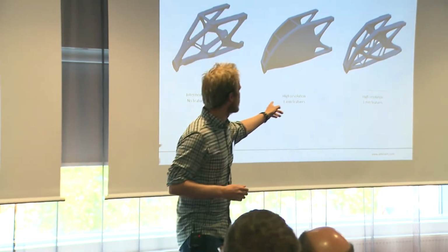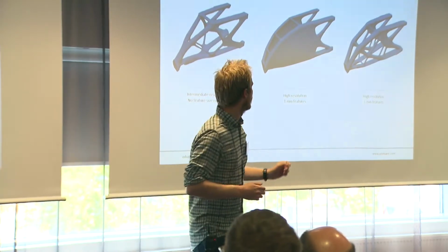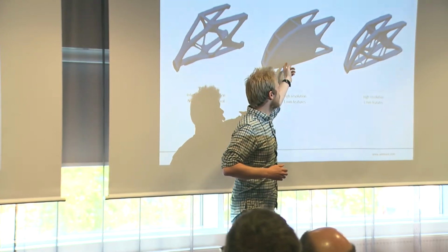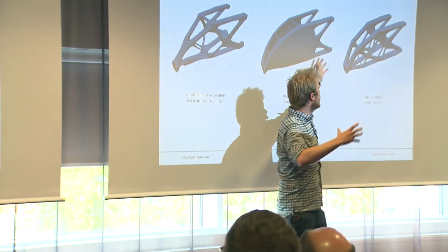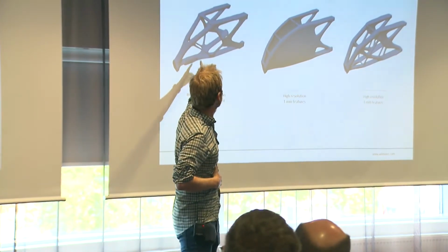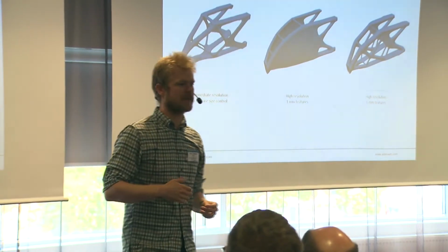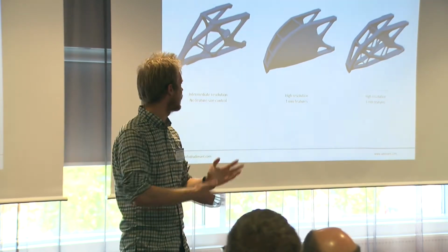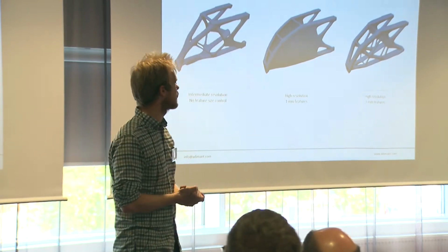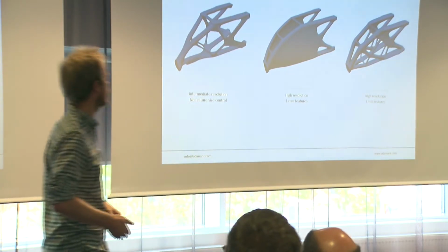And then something funny happens. If we still stay at the high resolution but increase the feature size, then this wall, which is maybe 1.5 millimeters thick, is not allowed anymore, so it's punished, and then the material starts to contract into rods again. We end up with a design which more resembles this over here, but now in a much more controlled manner, because now we are exploiting the design space and the capabilities of the printers, and we end up with a really nice and smooth design which is ready for 3D printing because it's optimized and designed at the same resolution as the printer.